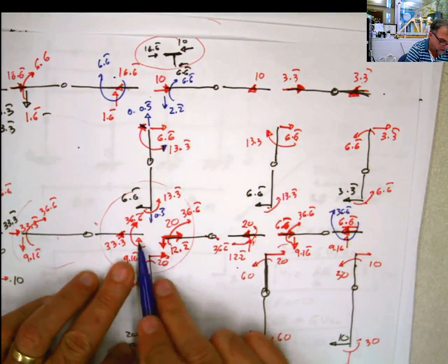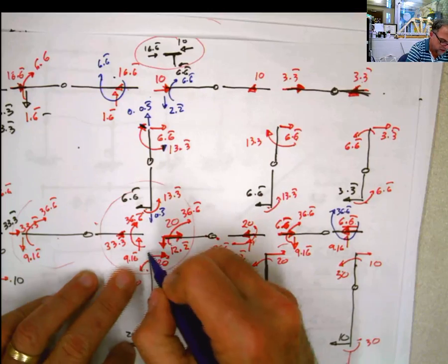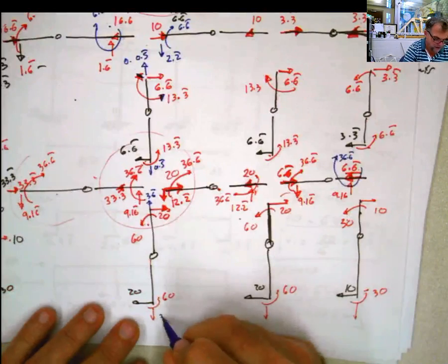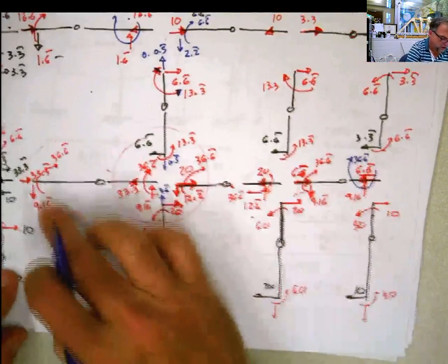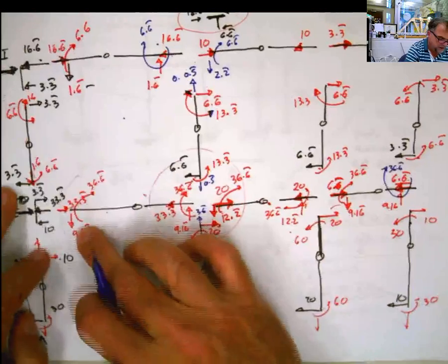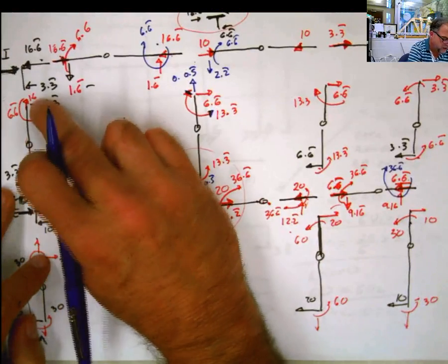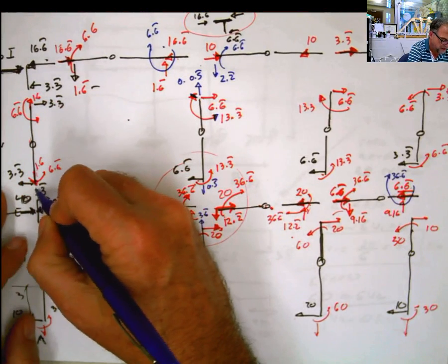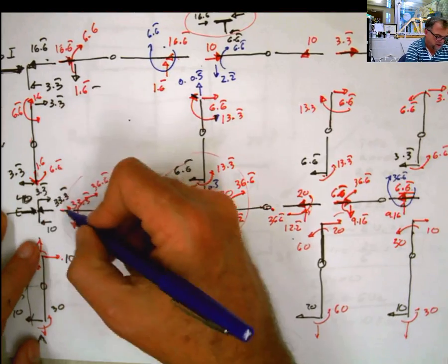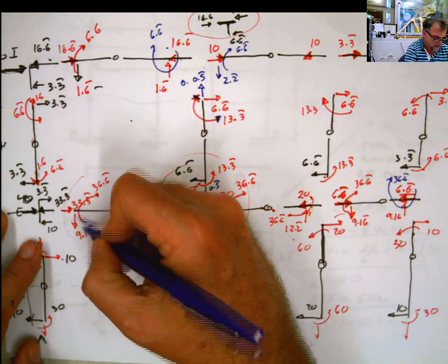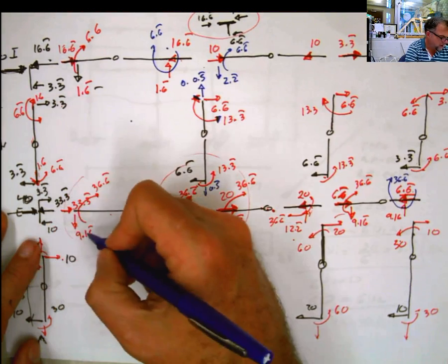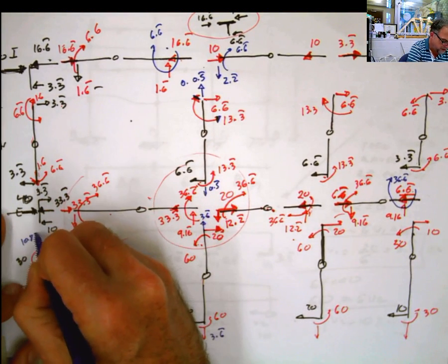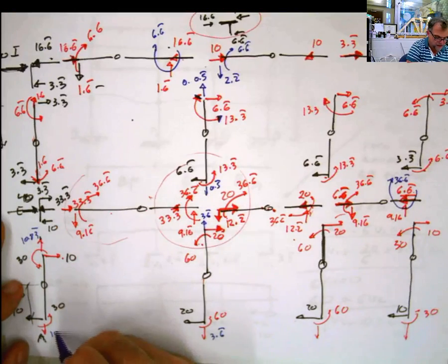I know this, I know this, I know that. Summation of forces in that joint. So this is 3.6 in that direction. And guess what? This value is 3.6 in that direction. Do the same thing here. I have this value, I don't have the vertical one. Yes, I do have it because I calculate that 1.6, meaning this one here has to be the same 1.6. If this is 1.6 here and this is 9.16, when I transfer it to this way, this is going to be 10.83, and it has to be in this way, 10.83, and summation of force in this direction, 10.83.